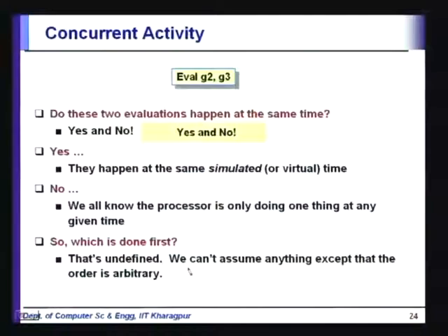So, then you might think that if they have different transport delays, then that can actually propagate through the circuit in different ways, and it is possible that we evaluate the same gate more than once in the same time, right. So, we are going to see how we can optimize on all that later on.